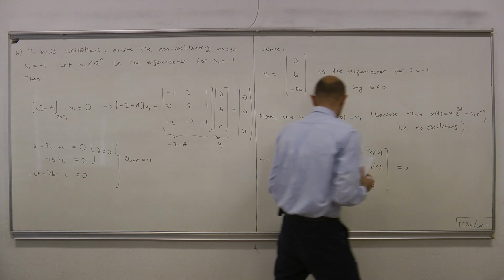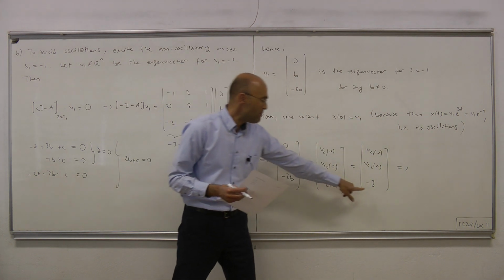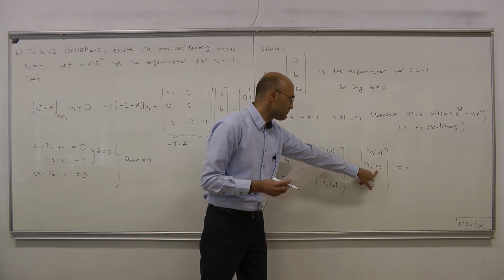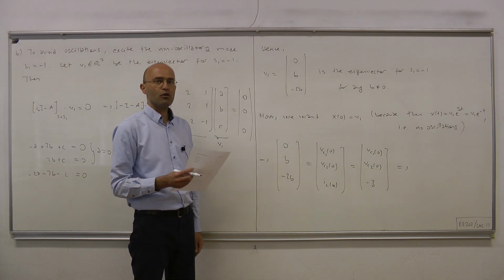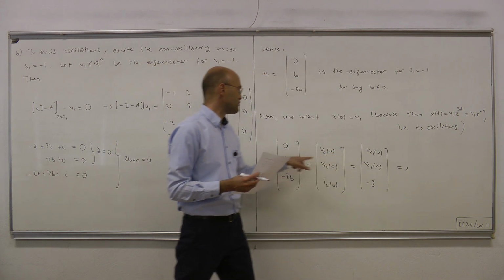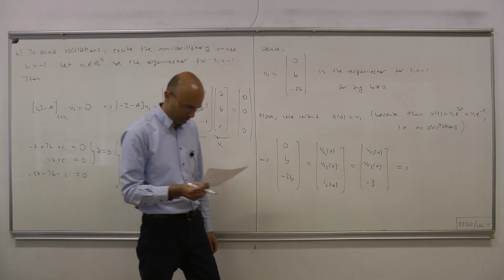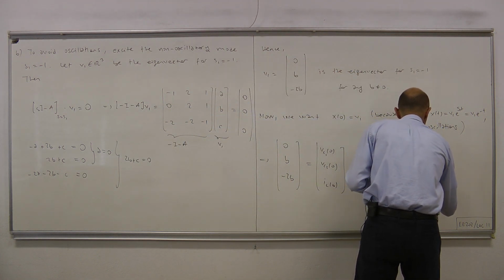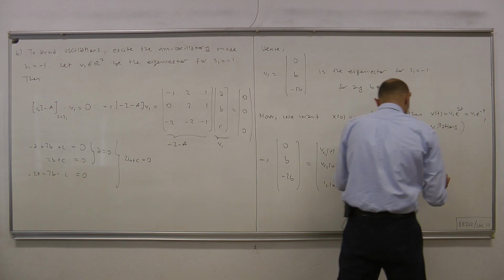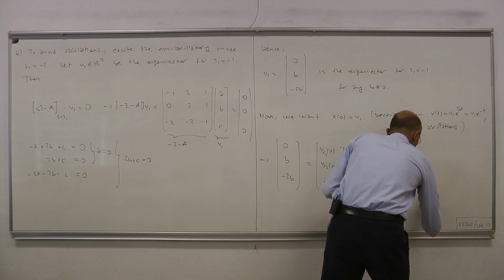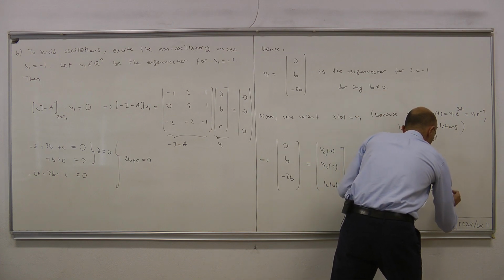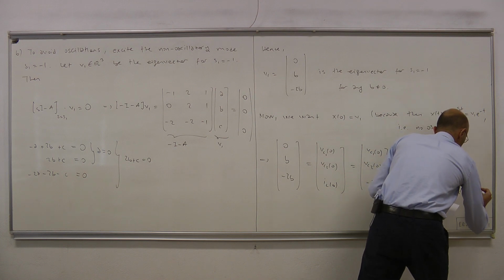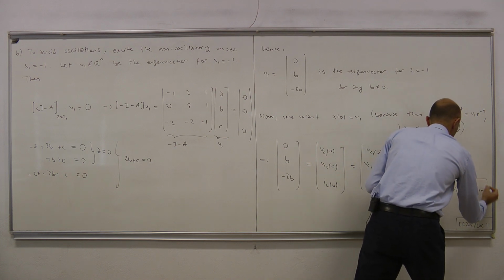So minus 2B must be minus 3, therefore B is 3 over 2. Hence Vc2(0) must be 3 over 2 volts and Vc1(0) must be 0 volts. Therefore B equals 3 over 2, and then Vc1(0) equals 0 and Vc2(0) equals 3 over 2 volts.